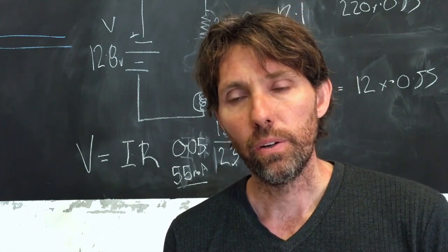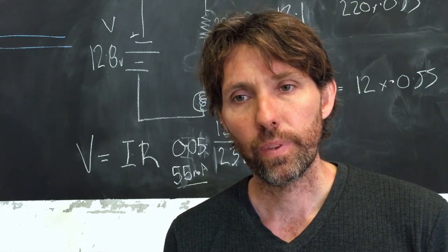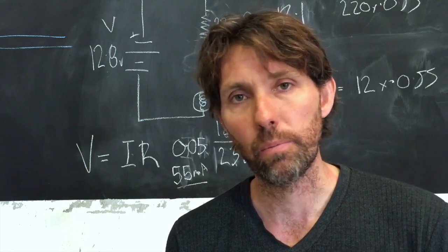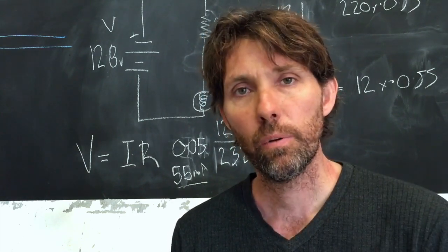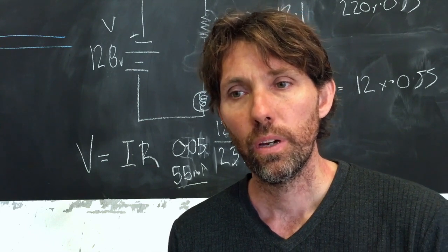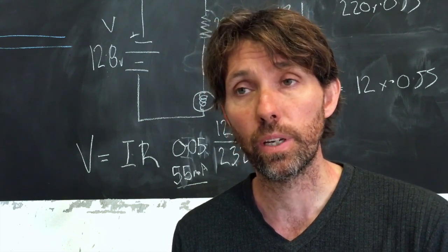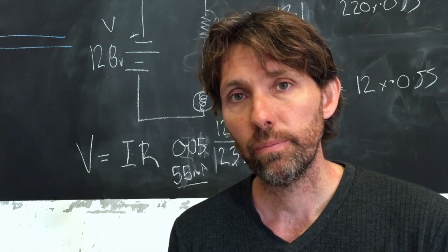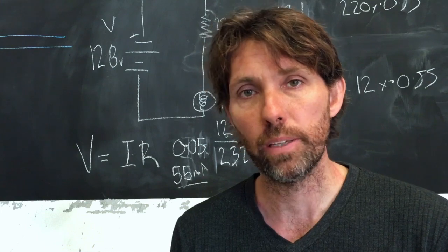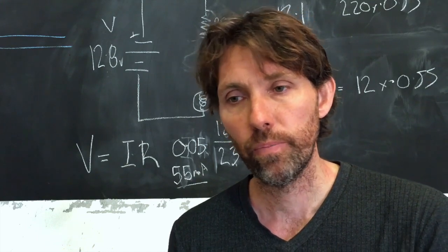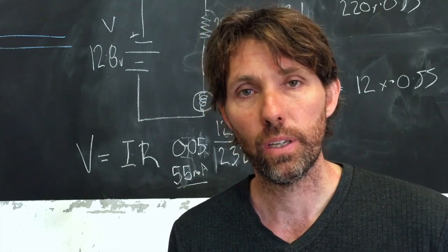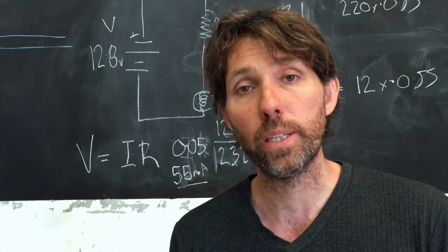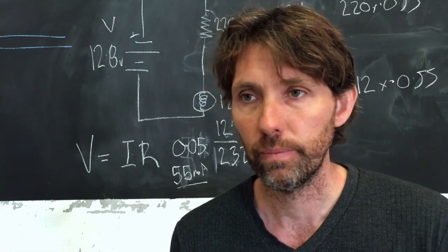Obviously, the circuit's only going to run as well as the voltage you're actually getting from the battery. So if your battery's good, that's definitely the number one place to start. If I was to distill this down to a few principles I'd like you to take away, they'd be that in any circuit, the battery voltage always drops from A to B, from the positive terminal of the battery, through whatever you have in the wiring, to the negative terminal of the battery. All the voltage drops across the different parts of the circuit will always add up to the battery voltage. That's the way it is.